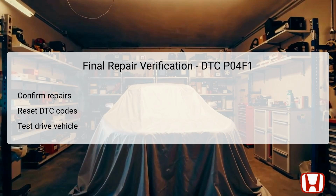Following successful repairs, the technician should reset the DTC codes using an OBD-II scan tool. Subsequently, a test drive is essential to ensure that the vehicle runs through all necessary driving cycles, allowing the PCM to monitor the EVAP system health. If the check engine light does not illuminate after several runs, the repairs can be considered successful, and the issue should now be resolved.